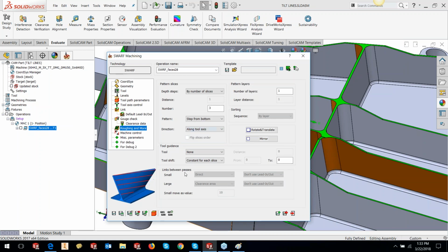In any case, we are going to use it along the tool axis. We are not going to provide more number of cuts radially, but we are going to do multiple cuts axially along the tool axis. We also have a possibility to provide radial roughing. That means I can have more than one depth, sidewards depth. I can generate 3 or 4 passes so that the material is removed gradually. It depends on how much material is remaining.